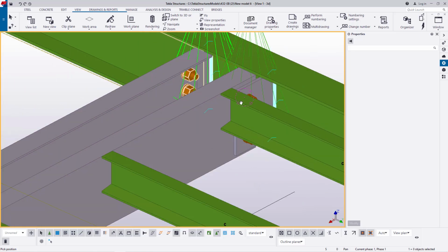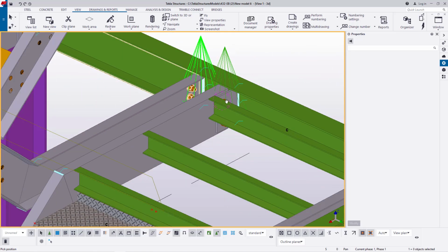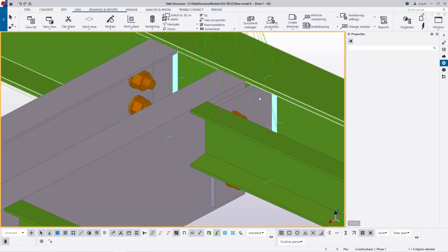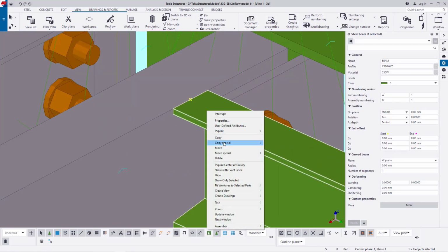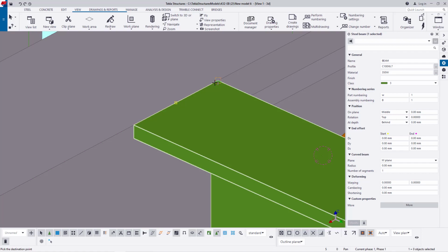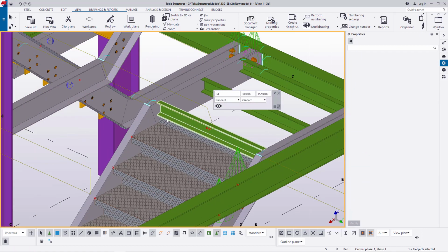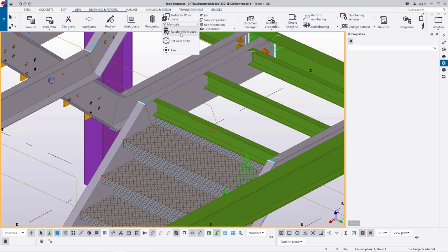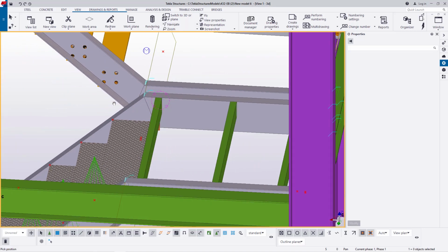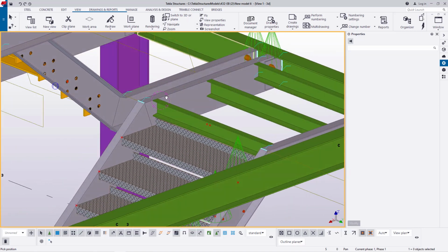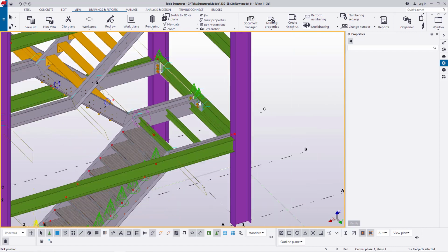This will be welded directly to this, or with the fin plate. We can even move it further away from that. Perfect. And that's all. So on top here we'll place a plate, a checker plate on the landing here.